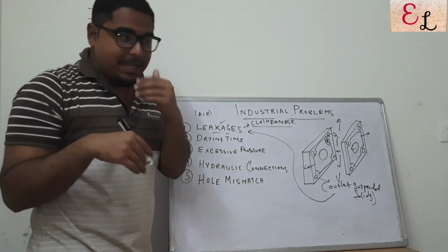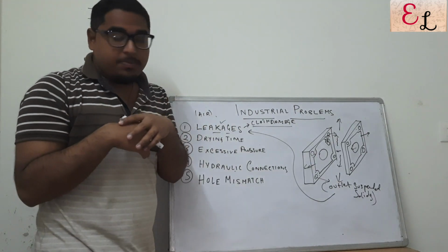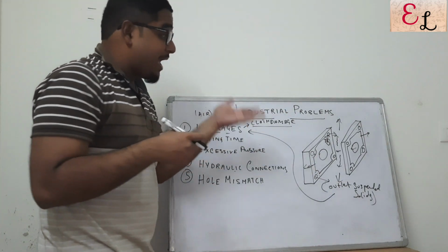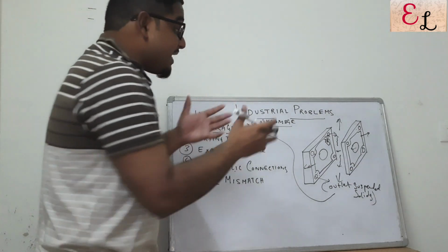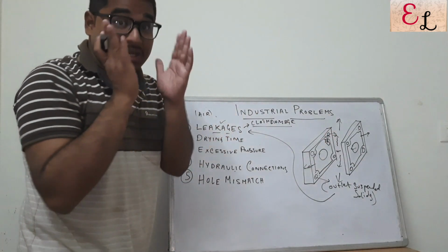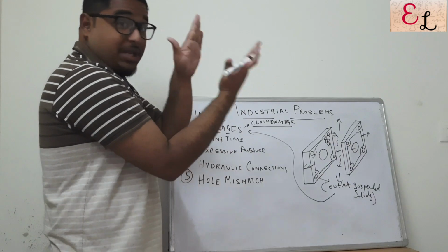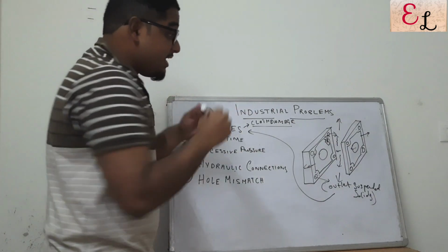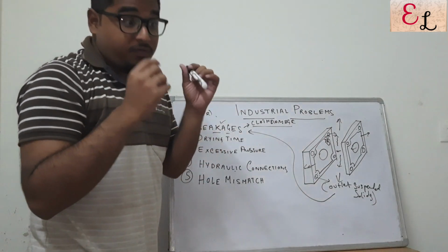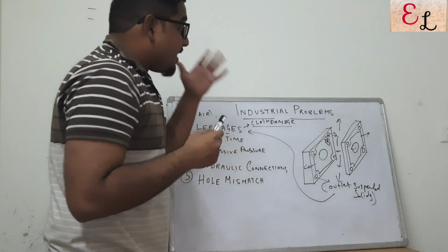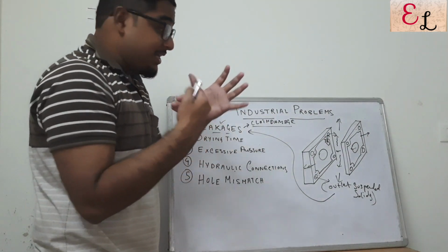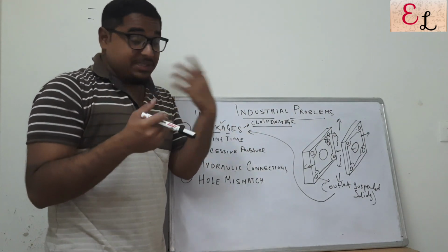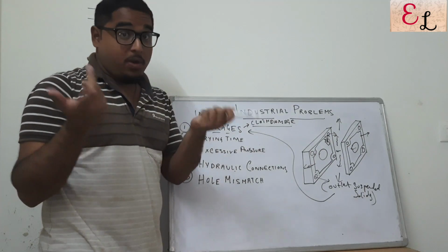So in that case, the liquid will splash out of the system and you will not get the outlet at all after a certain point of time, and that will also damage the filter press cloth by creating excessive pressure on it. Two plates are closed with each other in high pressure contact, and even then the liquid splashes out of the corners of the filter press, so a heavy pressure is developed on the cloth itself, and it's not getting enough space in the cloth and tries to escape through other spaces.